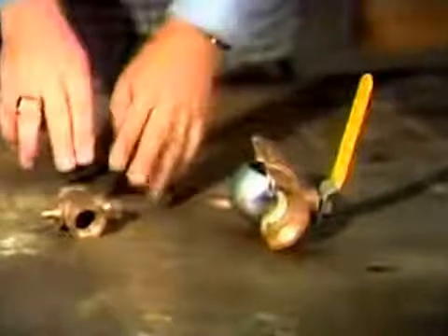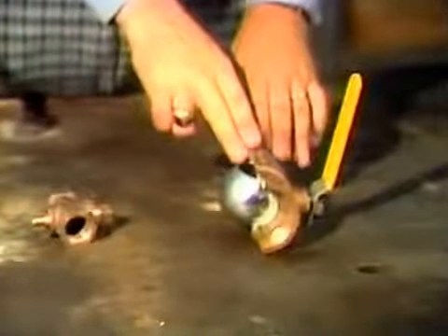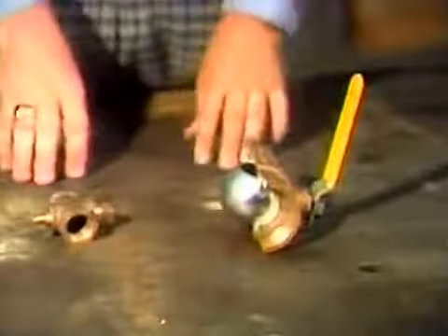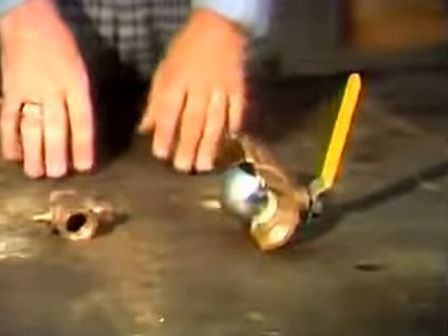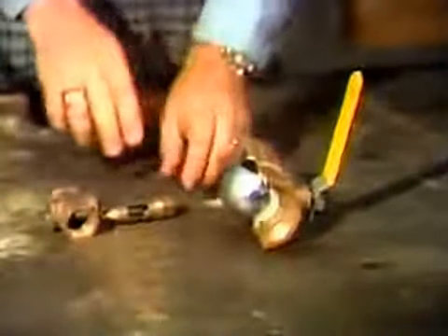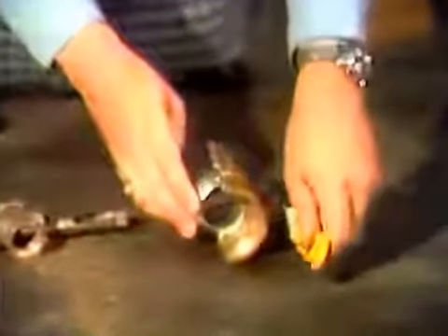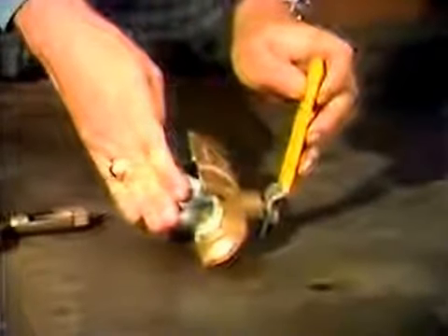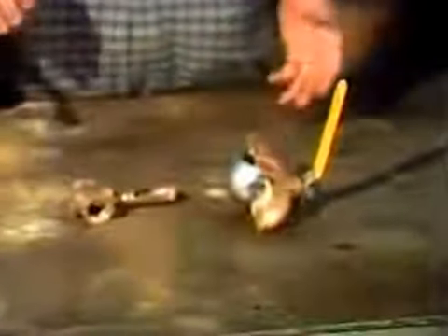Now we're going to look at two valves that are very much alike, a plug valve and a ball valve. In contrast to most other types of valve, they do not have discs which raise and lower. The plugs on these valves, or the ball in this case, open by rotation. When the valve is actuated, the ball makes a quarter turn, starting and stopping the flow very quickly. Usually this design does not provide the same tight sealing quality of the globe valve, but these valves aren't generally used in systems requiring a tight shutoff.